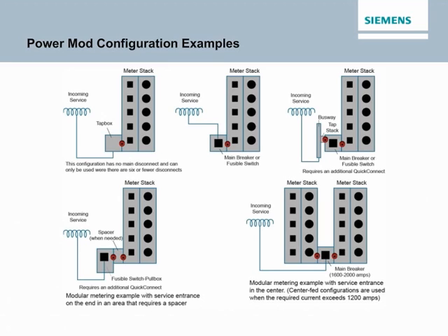A tap box provides a direct connection to the cross-bus and does not provide any overcurrent protection. A tap box should never be used to feed a main device, module types WS, WB, WES, or WEB, as this would bypass the overcurrent protection. Configuration 1 uses a tap box and does not have a main breaker or main fusible switch, which is permissible as long as there are 6 or fewer disconnects.